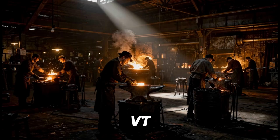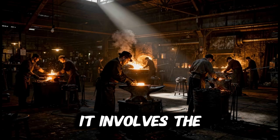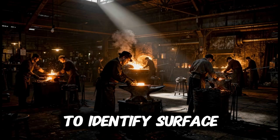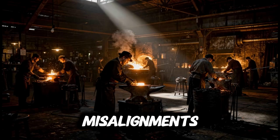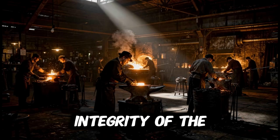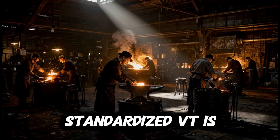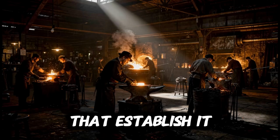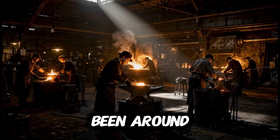Visual testing, or VT, is the oldest and most widely utilized non-destructive examination method in modern industry. At its core, it involves the systematic examination of a component, structure, or joint to identify surface discontinuities, geometric deviations, corrosion, weld defects, or misalignments without compromising the integrity of the material under evaluation. While it may appear intuitive, standardized VT is grounded in optical, physiological, and procedural principles that establish it as a reproducible technical discipline.